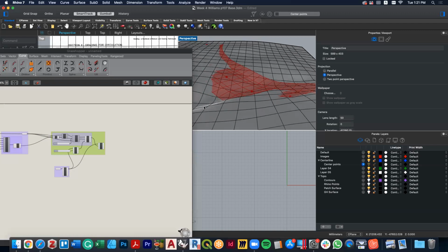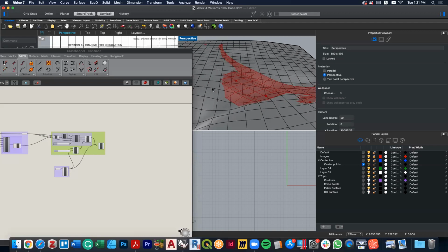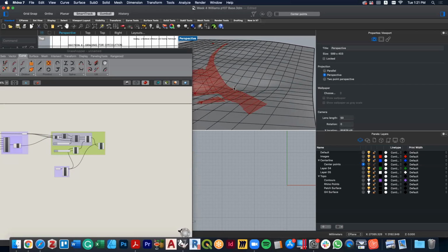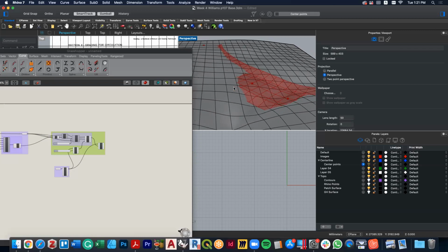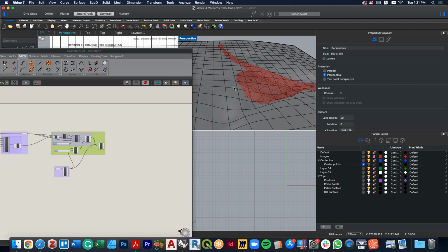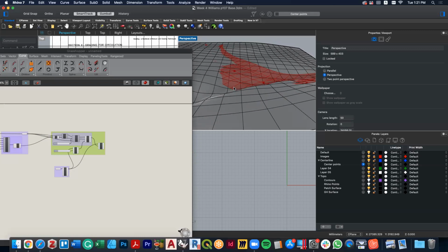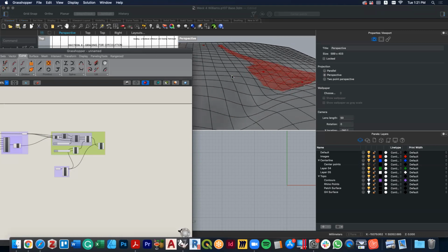What we can see is that, yes, there are parts of fill, but in actual fact, most of this is in cut. And this is what we're going to do for the class in Studio: part of this exercise in the grading subject is to work out how to make this best fit. One of the most obvious ways to do this is to begin the process of moving points up and down.